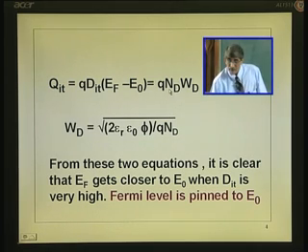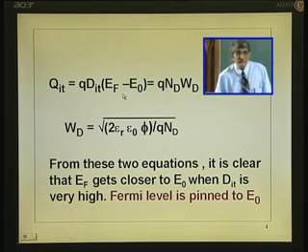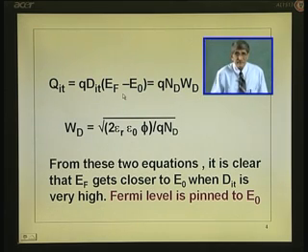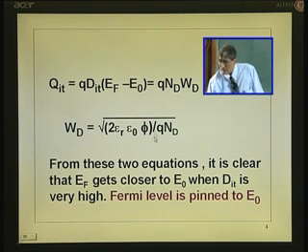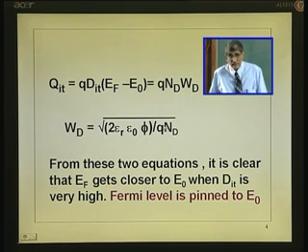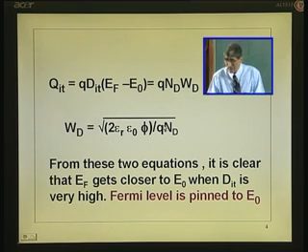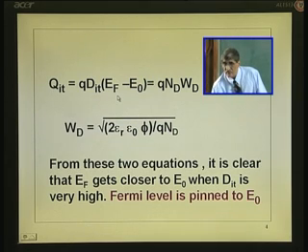Okay. So, for a given N_D you have got a phi there. What do you have on the left hand side? The left hand side has E_F minus E_0. E_F has changed its position, such that, substituting, the square root of q N_D twice epsilon_r epsilon_0 phi on the right hand side is equal to that quantity E_F minus E_0. Can you write E_F minus E_0 in terms of phi?